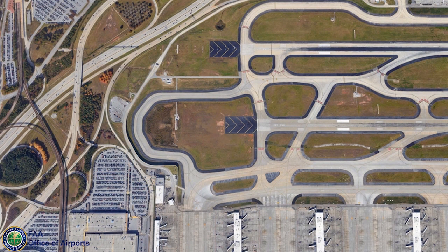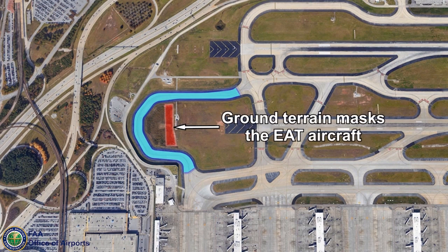The third example is an EAT at Hartsfield-Jackson Atlanta International Airport. A visual screen is not necessary for this EAT. The EAT's elevation is low enough compared to the runway end elevation that the airport's ground terrain sufficiently blocks the pilot's view of the aircraft on the EAT.